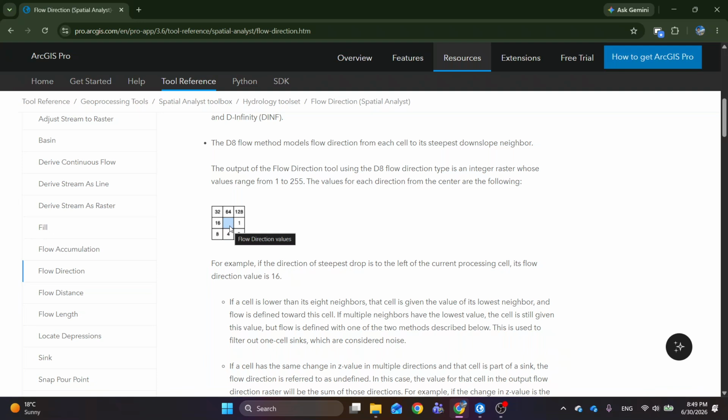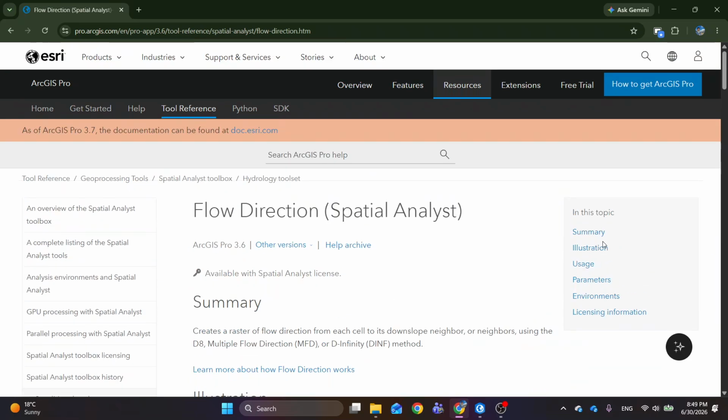there will be areas from higher elevation to lower elevation where the water can flow. Then if this center point is the higher elevation, among all these 8 cells, which would be the direction, the next cell where the value, or maybe the water, flows from this highest elevation to some other cells, right? That is how we are going to interpret this flow direction.